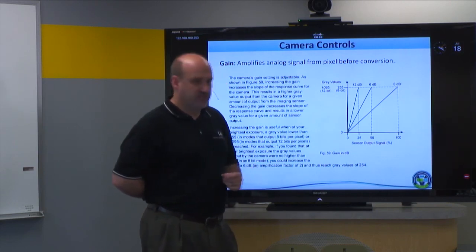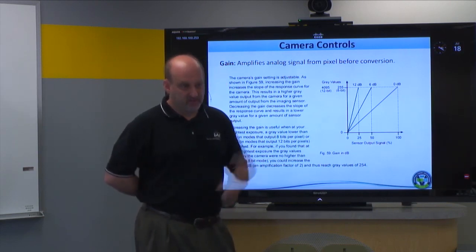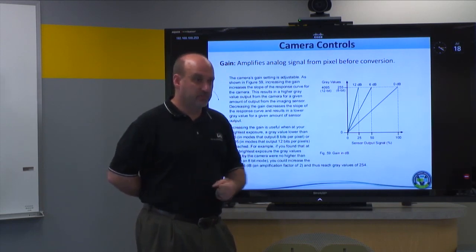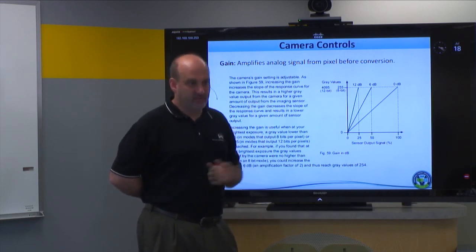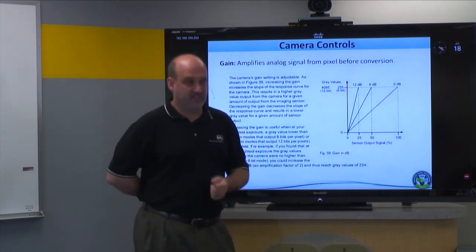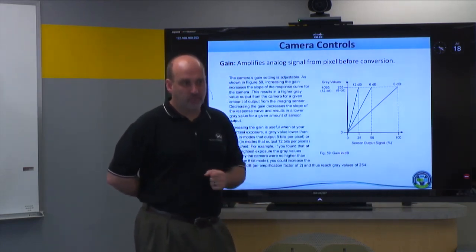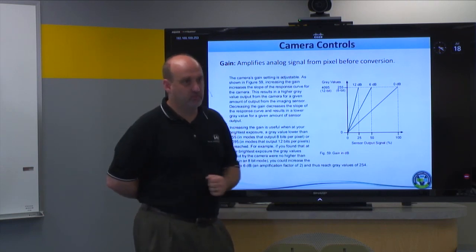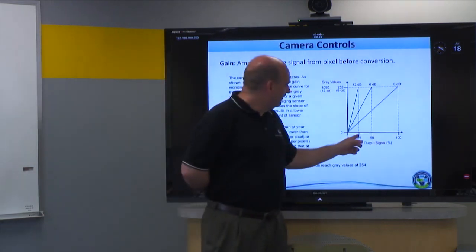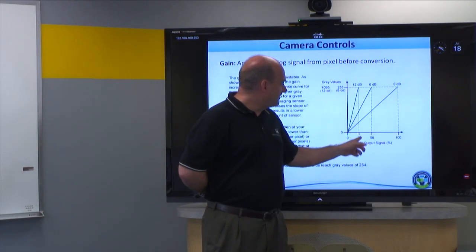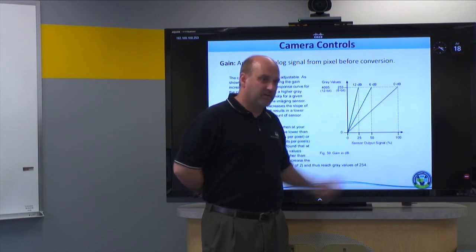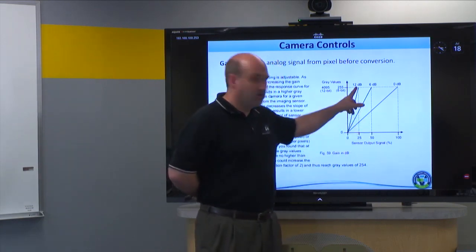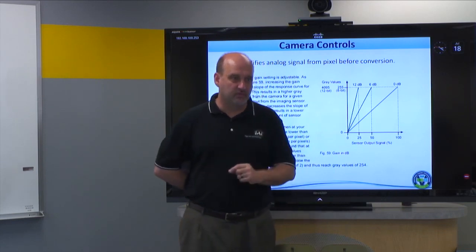So often in machine vision, we want high-speed electronic shutters to freeze the motion, but that also means we blocked out light. So if I take a 1/10,000th shutter and freeze the motion, like I showed in that motorcycle picture earlier, then that also means I only collected light for 1/10,000th of a second, and in 1/10,000th of a second, probably 40,000 electrons didn't register in my pixel well. So that means, hey, I used a high shutter, now I only got 10,000 electrons in my 40,000 well, so I'm only at 25% of that well, so how am I going to get my full output back? I'm going to apply 12 dB of gain and multiply that up and get a full scale count out.